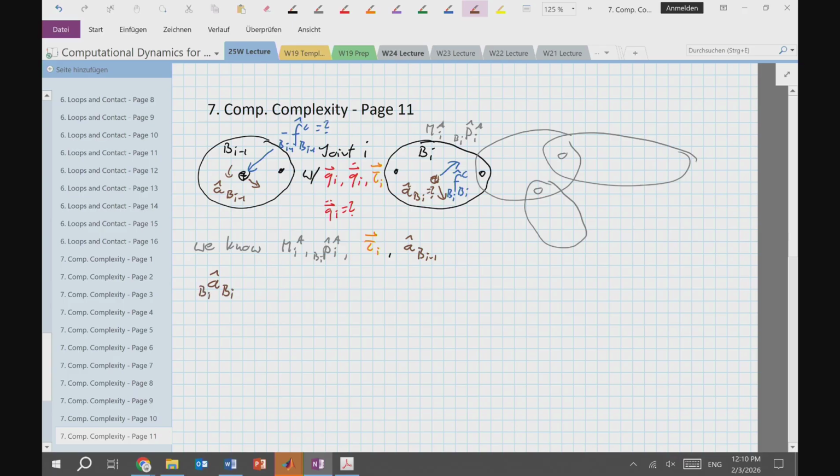We can at least write down our acceleration of our successor, which is going to be this transformation matrix from I minus 1 to I coordinates, BI-1 BI transpose, multiplied with the spatial acceleration of body I minus 1 in I minus 1 coordinates, plus stuff that happens at the joint, which I will write with this joint Jacobian J hat I, which will give me, again, quantities in BI coordinates.